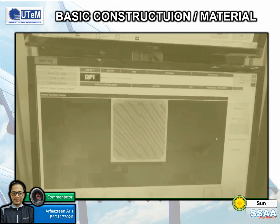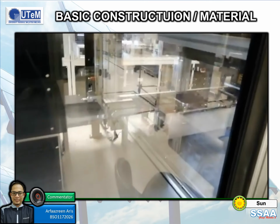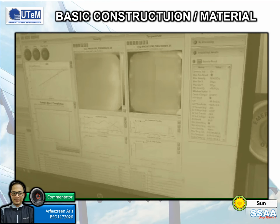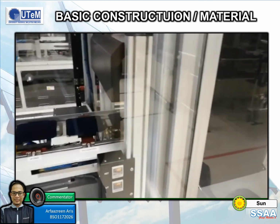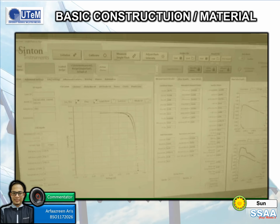In the testing machine, the solar cell will go to the cosmetic inspection. At this module, the solar cells will be segregated into 3 cosmetic grades. The solar cell will move to the PVI testing. After that, the solar cell will go to the hotspot test in order to prevent the solar cell from burning. The solar cell will then undergo the testing process, which is the last process.